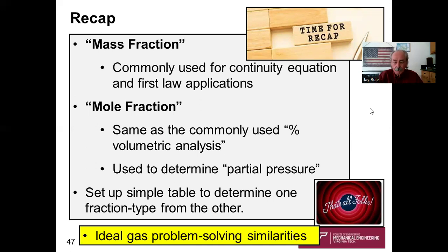So when you're reading a problem, recognize that the mole fraction is given to you if you see the word volumetric analysis. Also, mole fractions are used to determine partial pressures. So if you're asked to find partial pressures, that's where you're using mole fraction, okay?